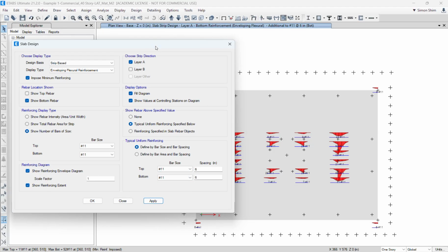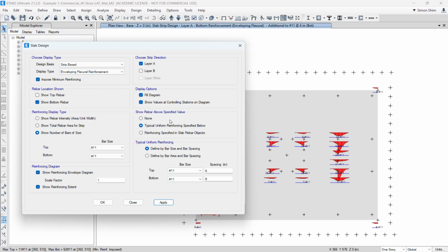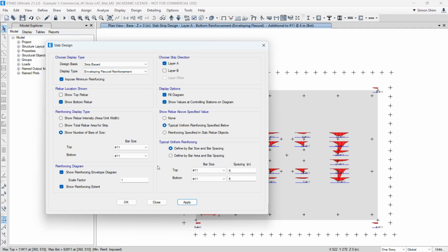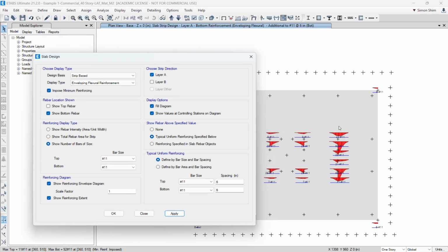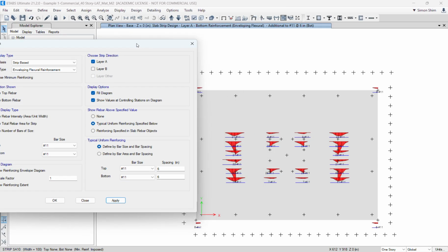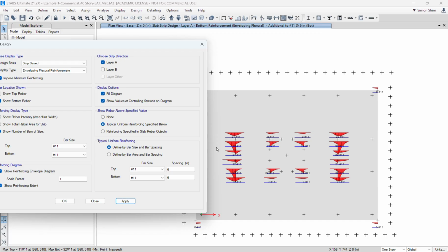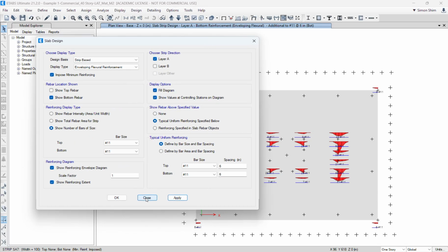So, all right. I think this is in general the mat foundation flexural bar design procedure. This is the only one we have. If you want to use a different method using some forces, you can play with the spreadsheet, you can do that too, but this is visually more intuitive. You can iterate and see and find out, and you can sum them up, and if you can place the rebar at the right location, I think that is general practice.